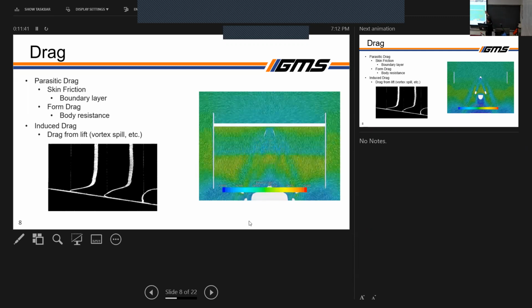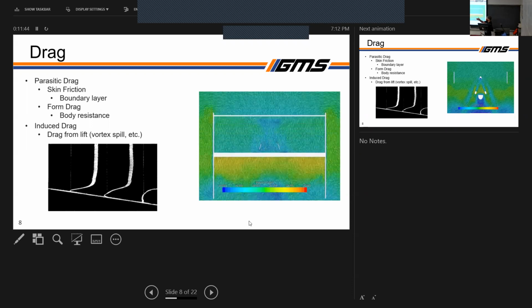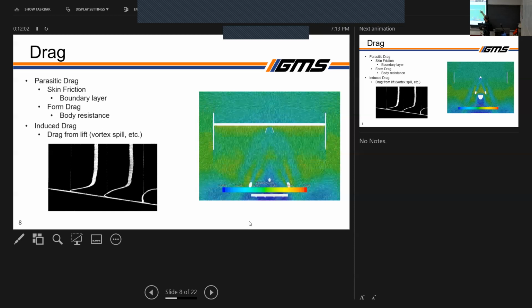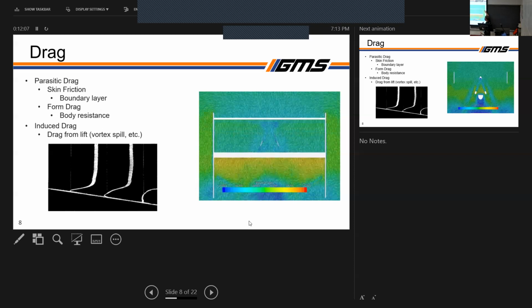So you can see as you move along the wing itself, you'll notice this region tends to form a very strong vortex. It turns out that this ends up inducing a lot of drag just simply because of how the change in momentum occurs. You can see we have a very low velocity, high pressure region here that ends up wanting to mix with this low pressure and this low ambient pressure out here. And that generates very strong vortices near the edge of our end plates, which is bad. That's something we want to try and avoid and mitigate if possible.